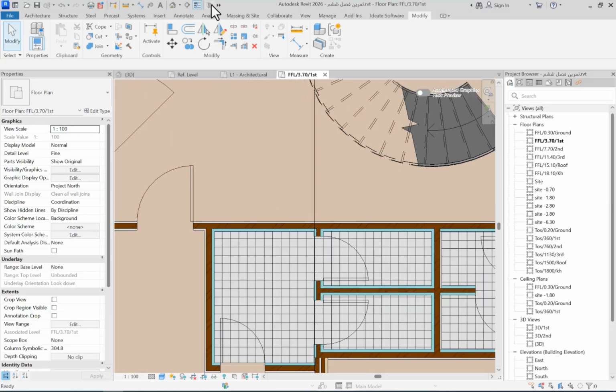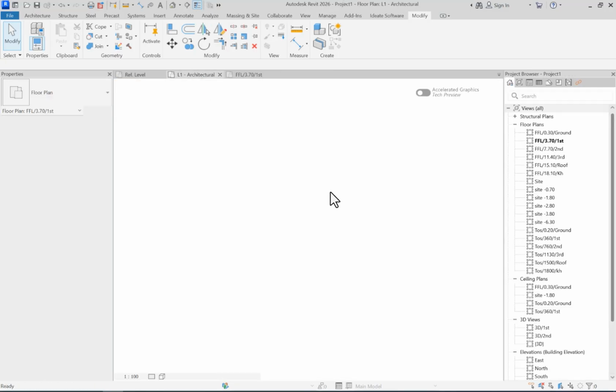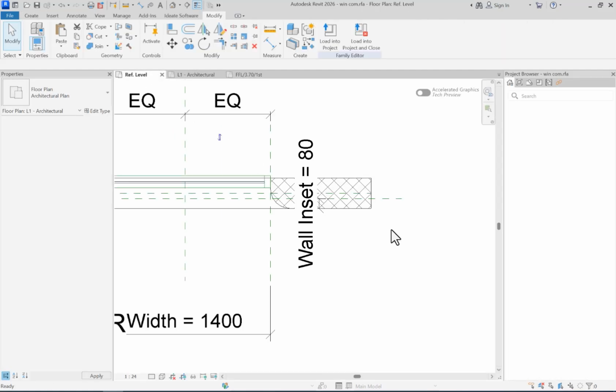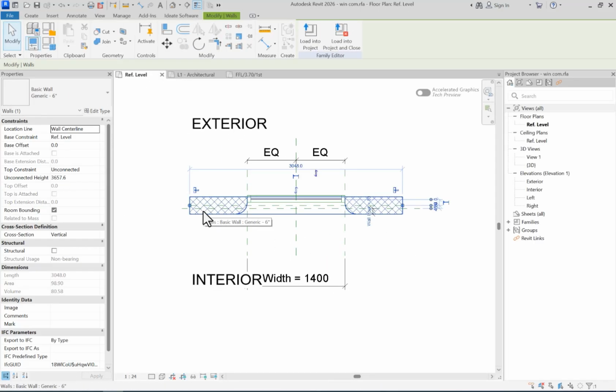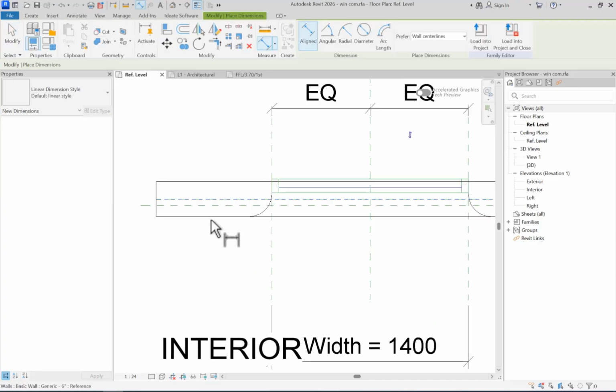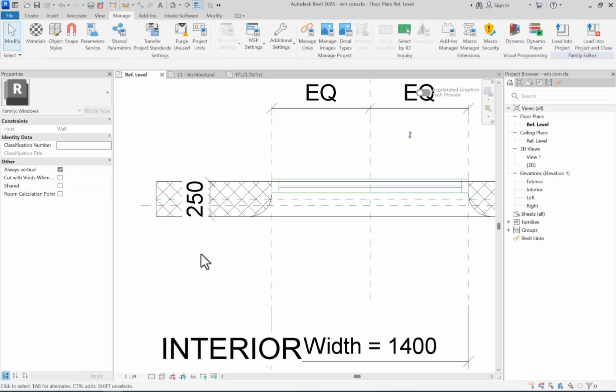If you recall, guys, I said that when we open up a window family, we would see a host wall. Now, you would be able to get some information regarding this wall, such as its size and dimensions. How? Let's see. What I'm going to do is move the cursor on these edges and press Tab. Here we go. This will be the thickness. Now we also need to give this a parameter. A very important point, guys: as for your parameter type, you should definitely go with a shared parameter.